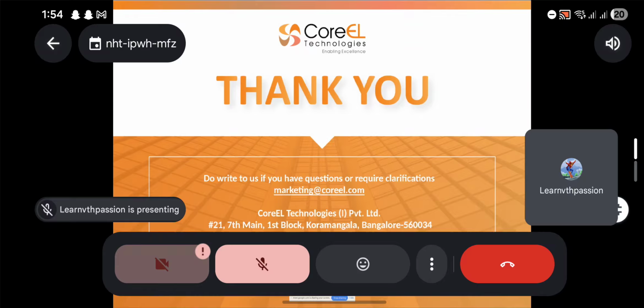RV is like a result view pane. In that we are going to check the M0 and M1 and M2, the details of the metal layers that are shown. Whenever you run the verification, two to three windows will pop up. In one window, the command transcript will be running, and in the same window you will get the final result. In some window, it will be showing the errors. When you launch Calibre, you will have four to five options, and all the options will pop up in a single go. I will tell you while running the verification in the practical part.